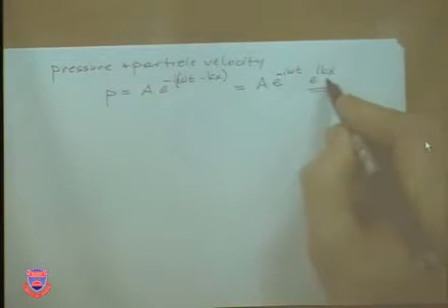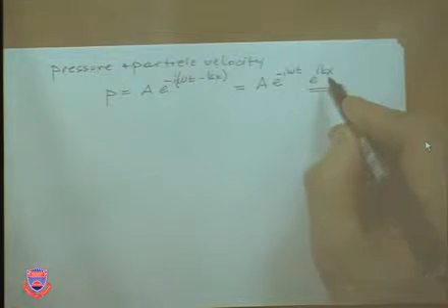If you were to freeze the pressure propagation in space, you look at this wave change, that's what the expression would be. Whereas the first one is in time. So if you're measuring pressure at a given location as it propagates, it will fluctuate as cosine omega t with a frequency omega. K here is the wave number, but it's a spatial frequency. Okay? So it shows how it changes over space.